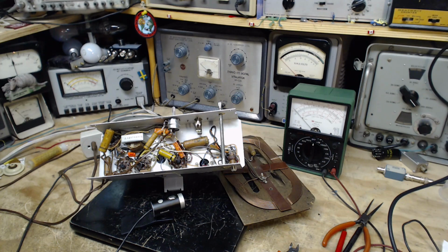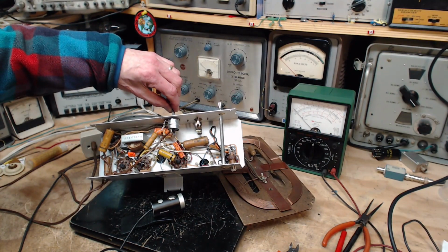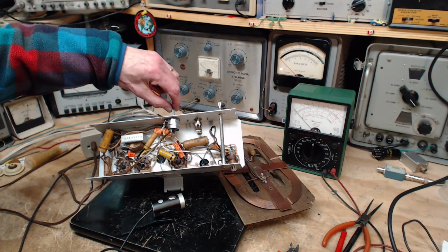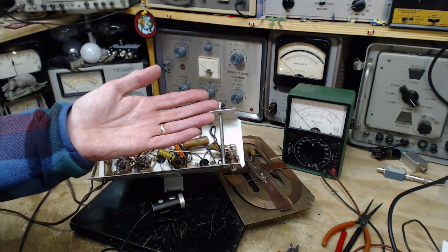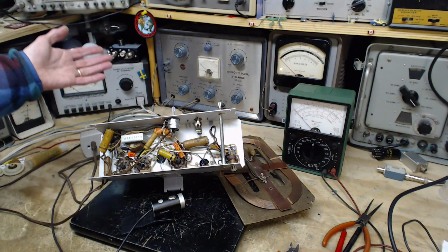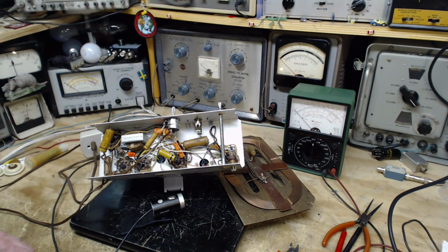Power is on. I'm going to give it the full power. Hey, we can play the radio, and does it play any different? Am I full of crap when I say these things? I'd like to know if I'm full of crap. That didn't sound very good. Look, that's the kind of stuff that starts happening. So I have a hum signal in me, and when I touch the radio, I share my signal with the chassis. I'm physically a lot bigger here. I'm a better antenna. So that's what happens when you don't have those capacitors in.